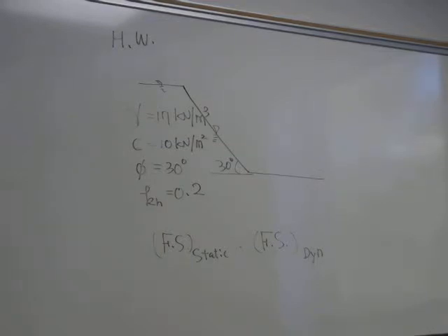If you want, you may use 100 different slices, 1,000 different slices, but usually somewhere 6 or 7 slices will give us enough accurate numbers. You could just type the equation in one time and then loop it 6 or 7 different times, and find out the line that shows the minimum factor of safety.